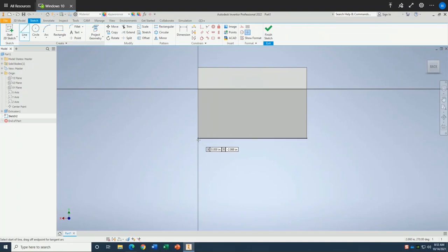I will start from the corner of the building, which is 0, 0, click, and try to draw as horizontal a line as possible, and that's going to be 1.5 inches. When the computer highlights the length of the line, I'm going to type 1.5, enter. And I will go all the way up vertically to the roof line, again trying to draw as vertical as possible. That's about 2 inches. 2 inches is highlighted. I click on it.